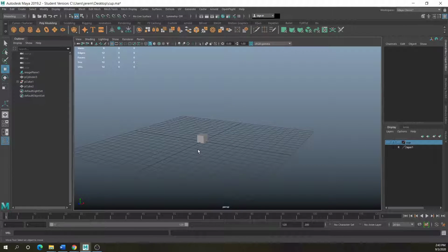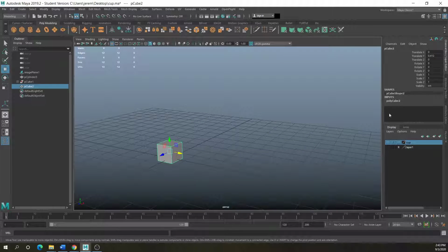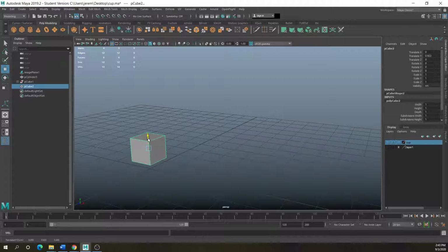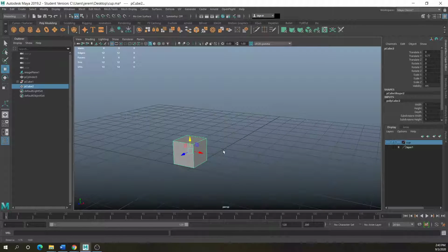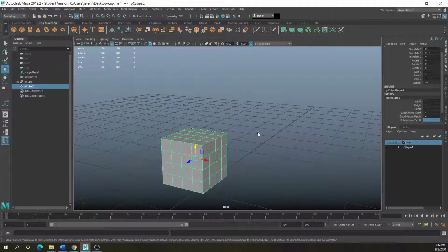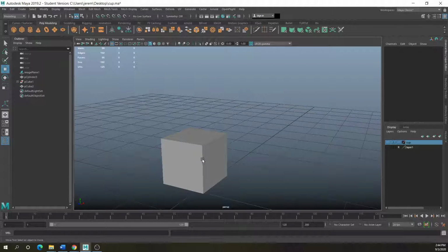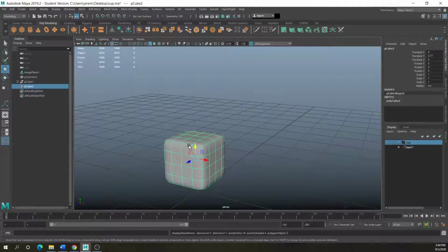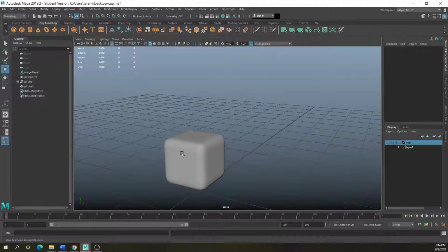First of all was the extrude tool. Then we'll talk about adding divisions. Say if you wanted to extrude some stuff from here and start box modeling out of this, you'd need to add some divisions over here, and you can do that just by typing some values here. Now if you were to collapse this box, you'd have a pretty nice little edged box.